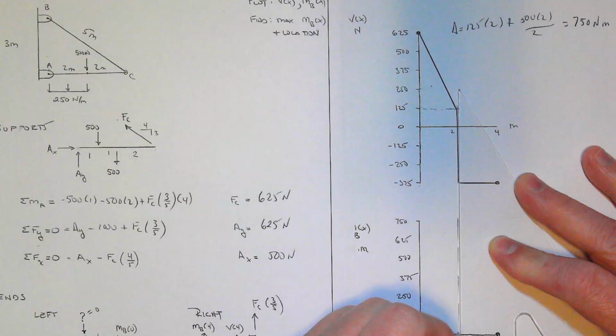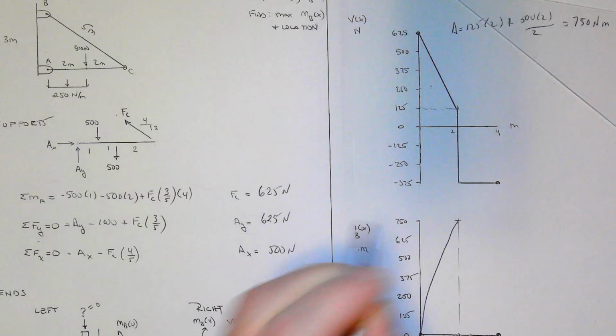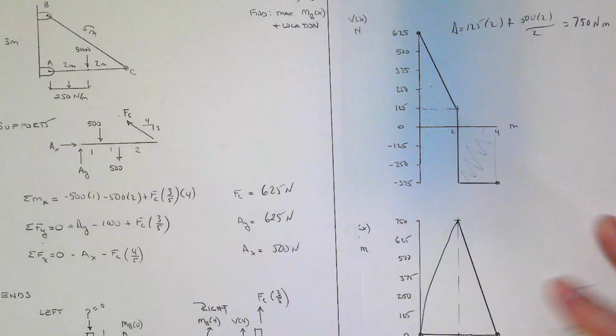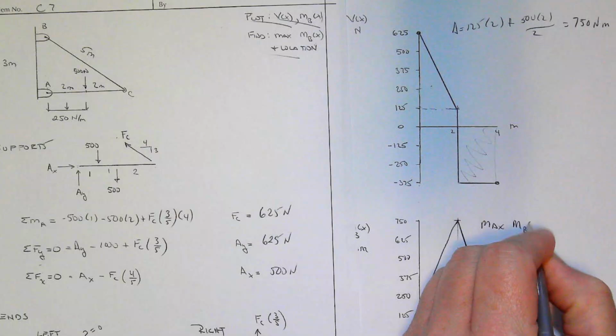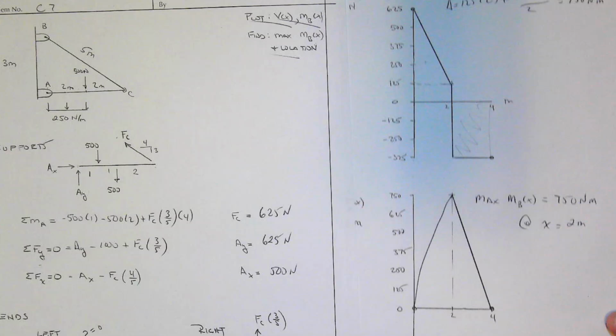But we're not done. There's a tendency just to write a force and another number and think, oh, I have a moment. No, this is just the y component we needed, and that's 4 out, so we multiply by 4. Okay, solve for FC, get 625 newtons.